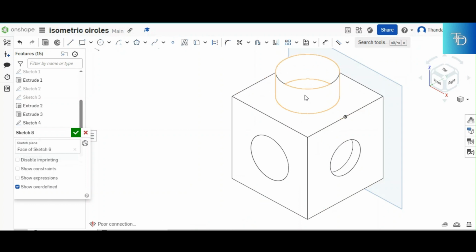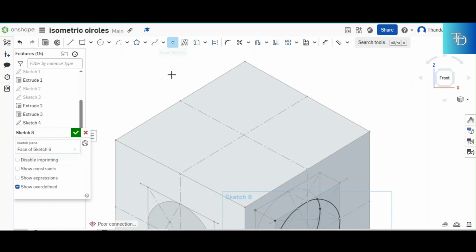Now let's carry on and come out with this cylindrical shape up there. And we're gonna take the height as what? As 25 millimeters. Now remember, we have our diameter 50 for the circles, so it's 25 from the center to the side. You mark 25. And then you mark another 25 from the center to the side. You mark another 25 from the center to the side. You are creating a cross. You mark another 25 millimeters to the other side.